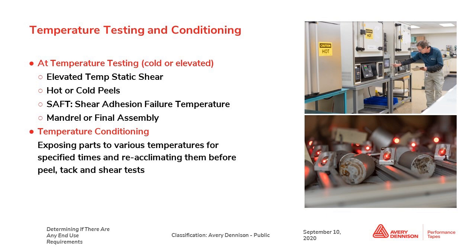If you remember what I was saying about rheology, adhesives will generally flow more at higher temperatures. Under the same load, the adhesive will likely fail sooner at the elevated temperature versus room temperature.